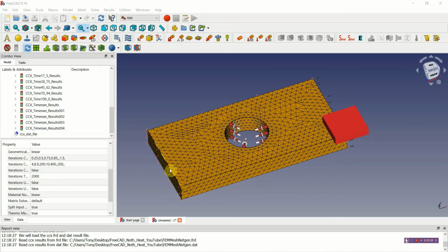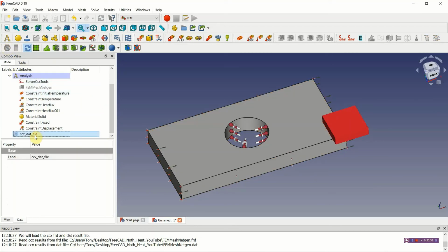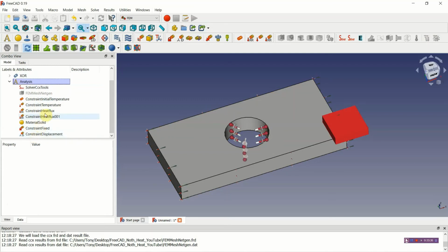Strictly speaking, you have to suppress 5 rigid body modes. So I'm going to delete all of these results. It's very dangerous to try and open those. Trying to plot things that are not a number is dangerous.